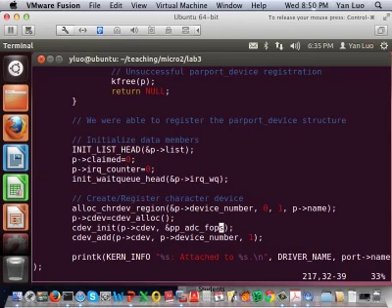So this device driver actually does two things at this step. First, it grabs or allocates the resource of the parallel port so that it can access the parallel port. The other thing is it creates a device, the character device, so that later you can use /dev/ppadc0 to access it. So there are two things it is doing right now.